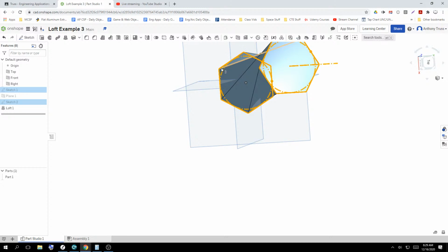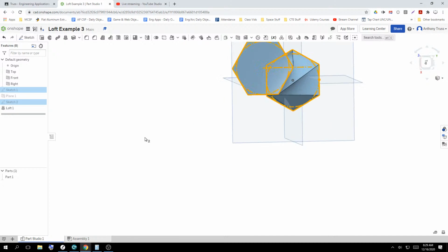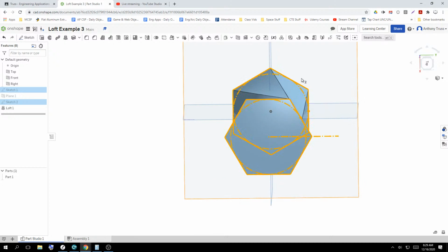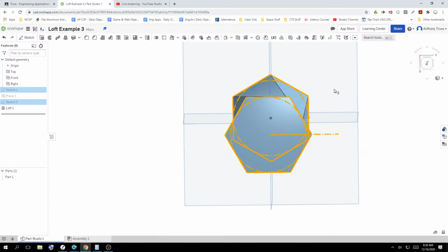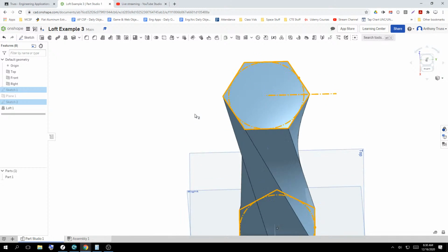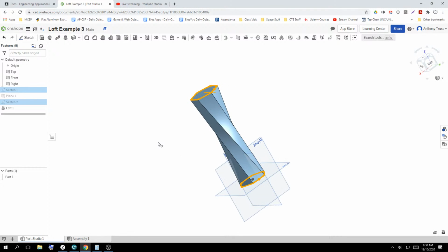But one of the sides is 1.5 inches long. And if you take a look at how I've arranged the sketch, I have vertical sides on one sketch, and then I have horizontal sides on the top sketch, but they're the same hexagon. The only difference is one is rotated, right, to have a face being horizontal versus vertical. I also have it set to 10 inches apart.